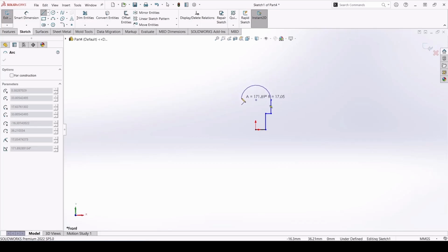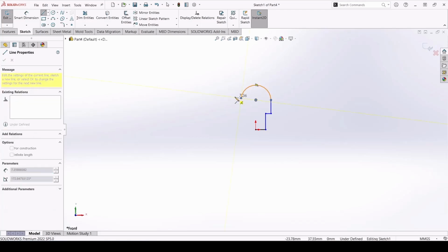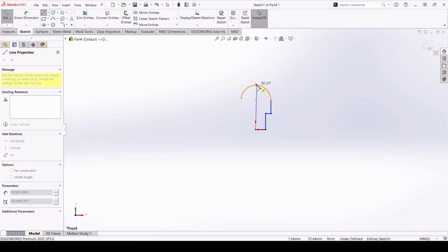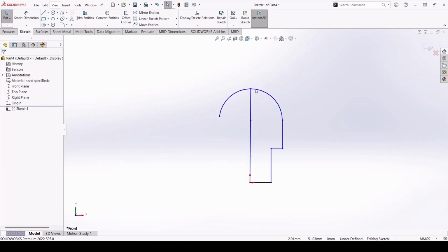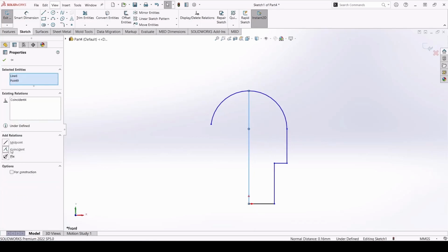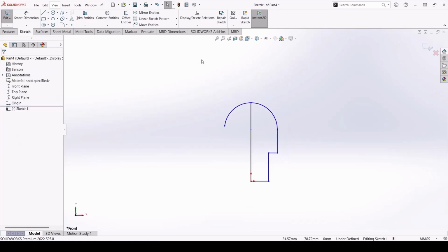You don't need to skip your sketch to create the arc. So now we can just create it that way. And voila, you're good. Click on escape and then go to creating one last line. So this last line should be vertical. Click on control key and click on the points and the line and make them coincident. So you should get something that looks like that.